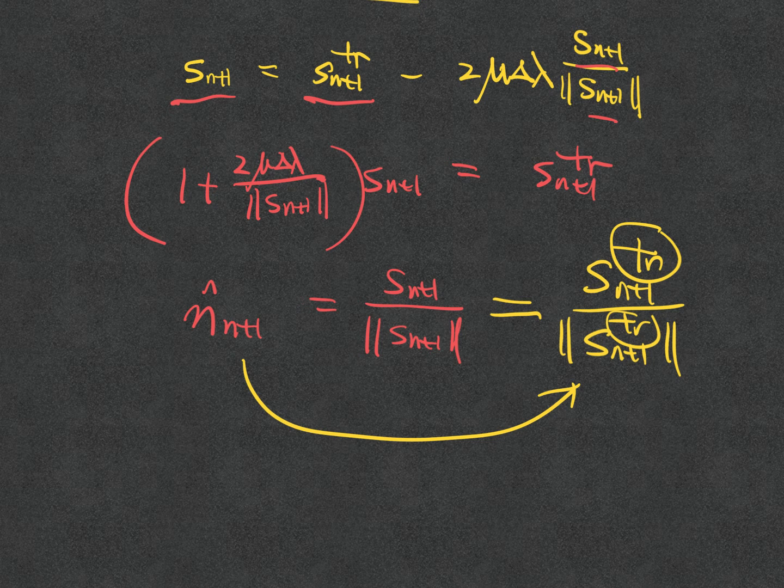Because if I have a yield surface as a circle, and I already know this is the n direction, it doesn't really matter. I have a trial state that is outside of the yield surface. I only need to go back to here, with the right amount of the correction term coming from that 2 nu delta lambda, and I can go back to the yield surface perfectly. The direction never changed. I just overshoot in the same direction. I just correct it back in the same direction, and then I will be on the yield surface.